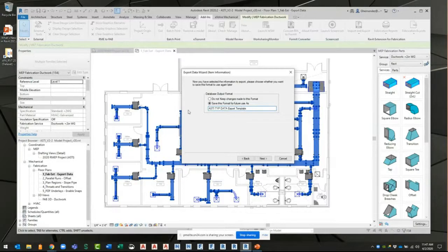You can create something, or not even do all this here, just use your company brand there. And I always, if you've ever been through my training, I tell everybody this about the branding. What I mean by branding is put your initials or something in front of this or at the end of it. It keeps it organized in Revit. It keeps them all grouped together. And when your new users come in to use this stuff, they'll know to use the company initials, instead of one that doesn't have that on there, because they'll know that that's the company standard. All right. I'll just click on next here.